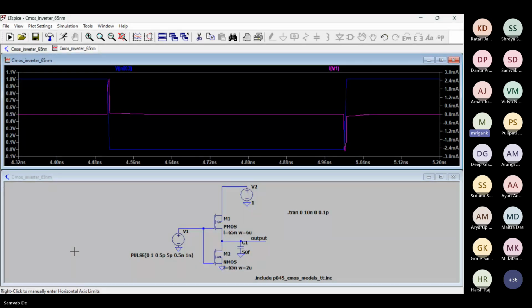Overall, these capacitors, at every point of the transient waveform, you can assume small signal behavior for different parts of the signal. Suppose the signal is rising up, for every small section, you emulate the small signal behavior. Overall, it's a large signal, but the rising section you break down into small portions and evaluate the small signal behavior. So you can apply the Miller effect between gate and drain. So that CGD will get broken and you can apply that CGD between gate and source.